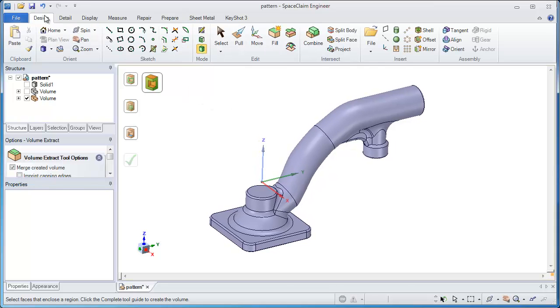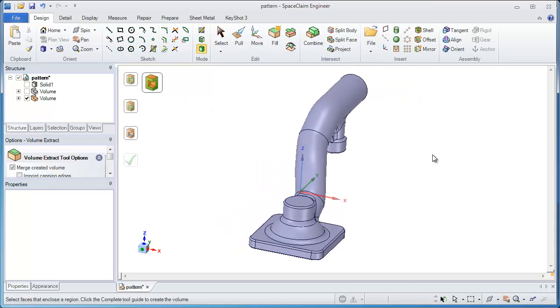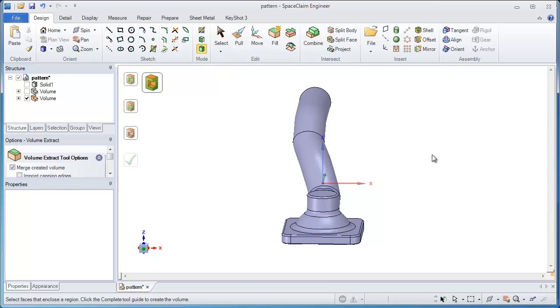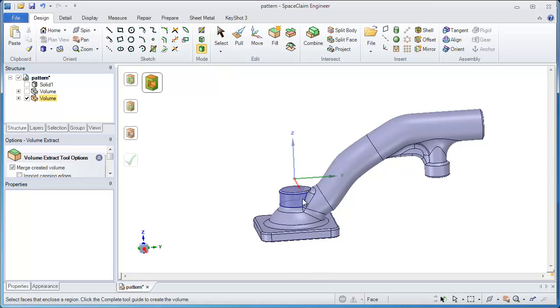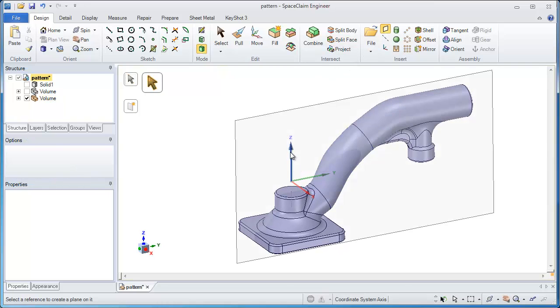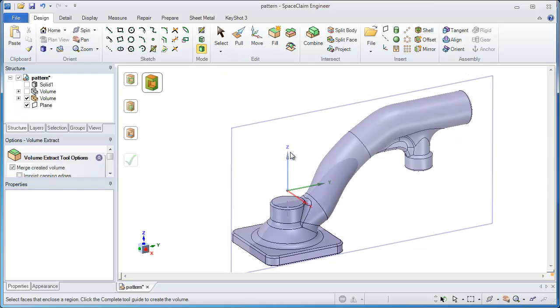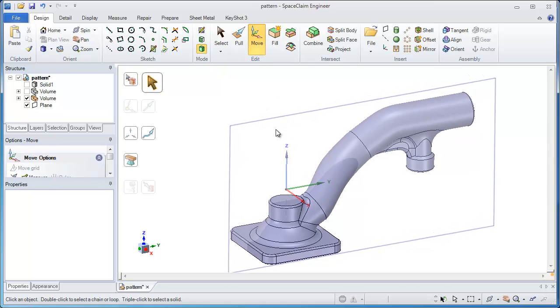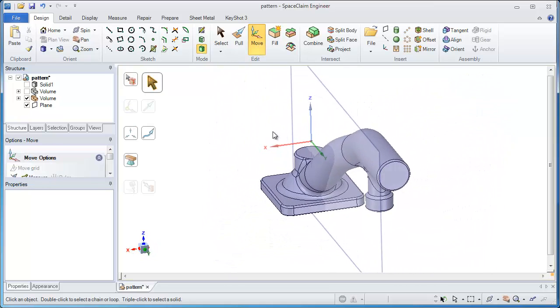So how would I create complex parting lines? Well, if I look at this model, I can see the back half and the front half, or let me put it in this perspective, the left and the right look fairly planar, but it's the section in the middle that's going to cause a problem. So we'll tackle the low-hanging fruit first, and we'll say on this reference plane, and I'll create another one, that's where my parting surface is going to be.